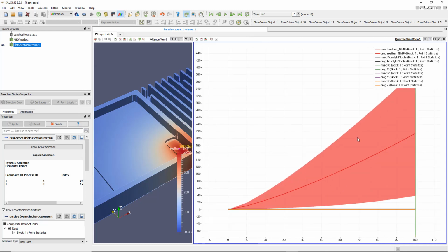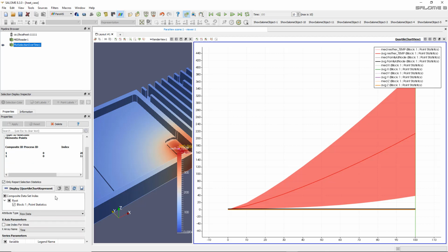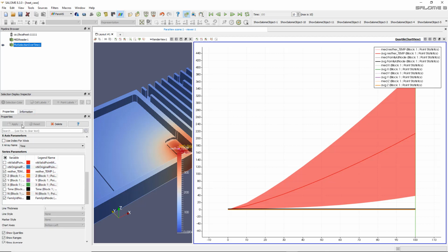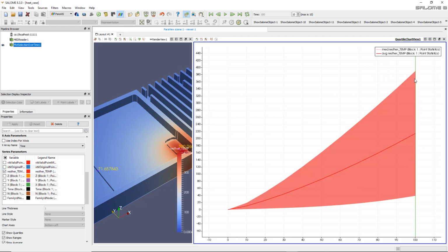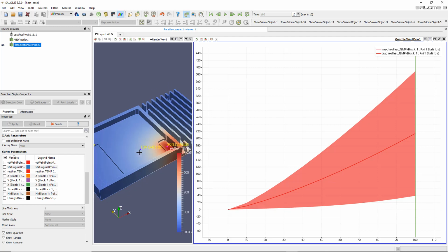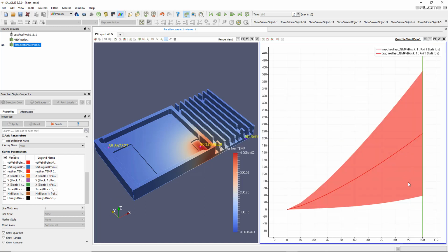This is the temperature, and in this properties window I will only display, let's say, temperature results. It gives me the results between the 2 points that I selected, so that's why I have this big red. The top result here is 300, and this is the point here. If I have only 1 point, it would give me one curve.